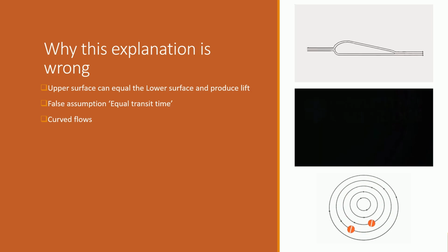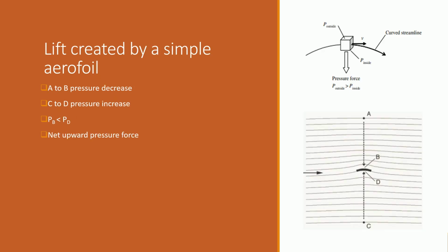This shows that on the inside of the curve, the pressure must be lower than on the outside. This provides the centripetal force needed to keep the flow in rotation. The pressure decreases because the velocity increases perpendicular to the curve as you approach the center of rotation. A simple curved plate can generate lift from this principle of curved flow creating pressure forces.